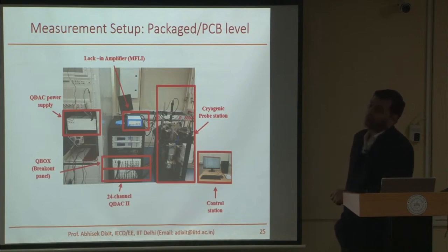Of course, you have to work with cryogenic compatible everything. Cryogenic RF probes are more expensive even than those for room temperature systems. You have to have cryogenic RF probe arms. You have to have cryogenic standard impedance substrate. The room temperature substrate also will not work.